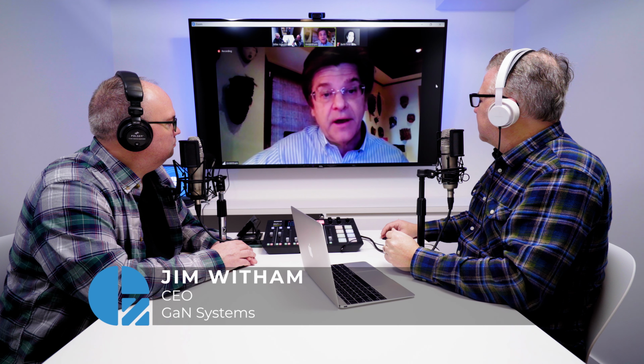And GaN does that a lot better. And the second reason is that when you switch really fast, you can make things small. All the electronic components get smaller when you switch at a higher frequency. That's the trick or the benefit that we use to make all these tiny chargers and tiny electric vehicle motors.